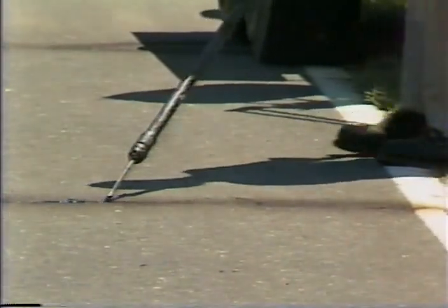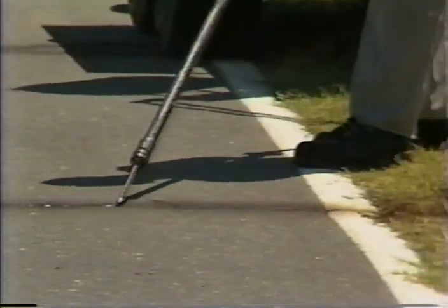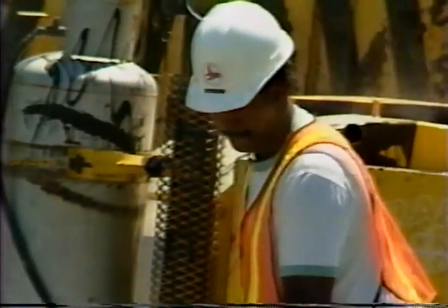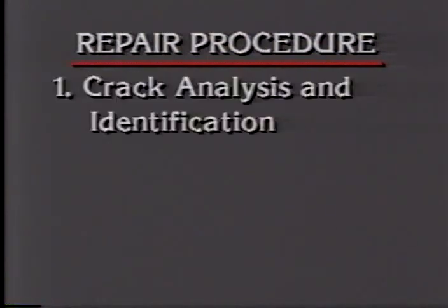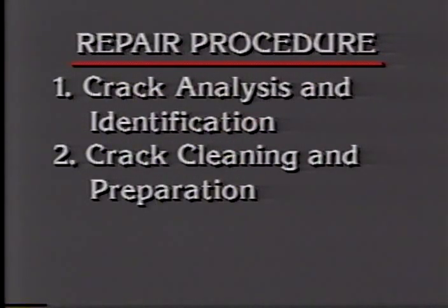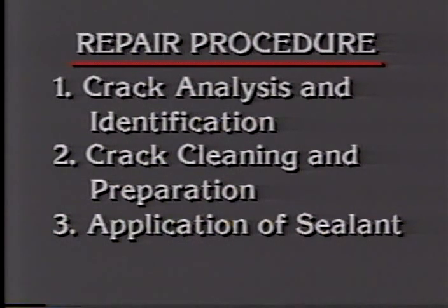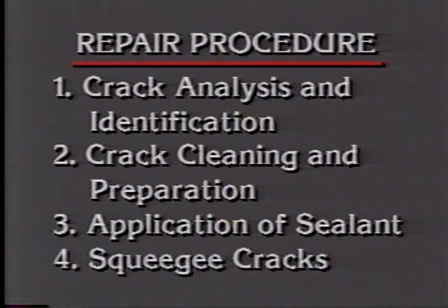A 4-step procedure will be presented for sealing cracks. Following these steps will result in effective crack sealing and an extended pavement life. The 4 steps are: 1. Crack analysis and identification. 2. Crack cleaning and preparation. 3. Application of sealant. 4. Squeegee cracks.